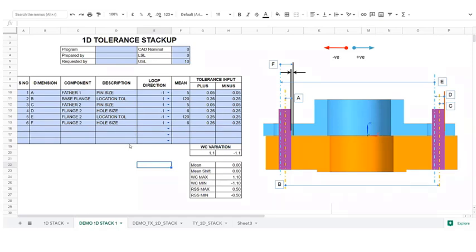So now our tolerance stack-up loop is completed, and we populated all the tolerances into the tables over here. So we started at the left of the gap, and we ended at the right of the gap. Okay, so now we included all the tolerances which are included in the system. Okay, now let's see the output of it.